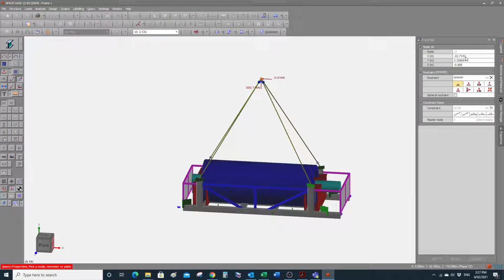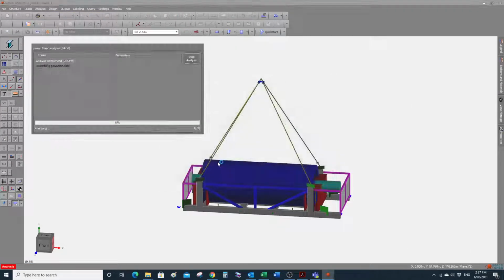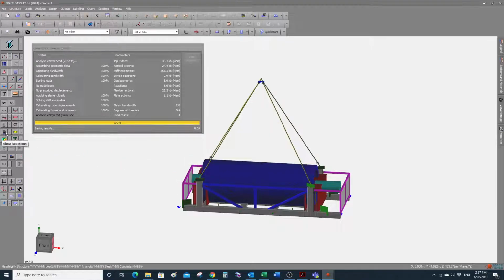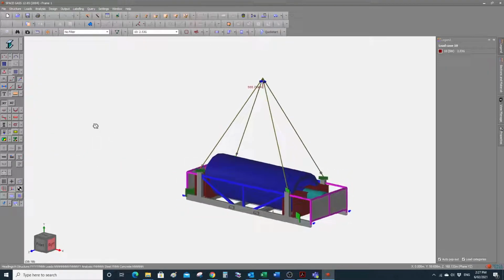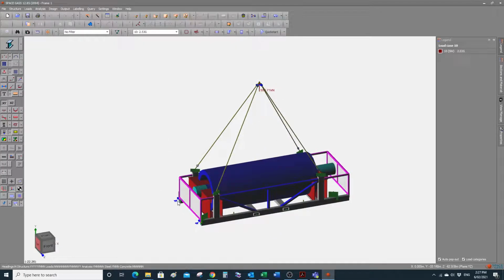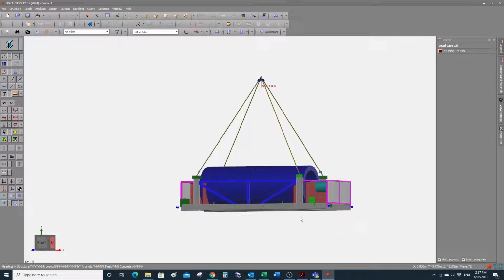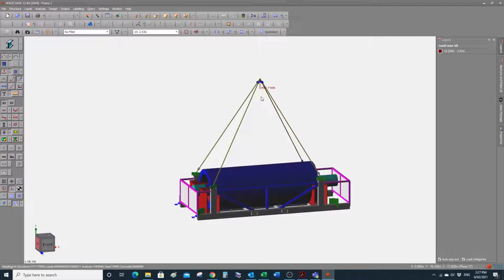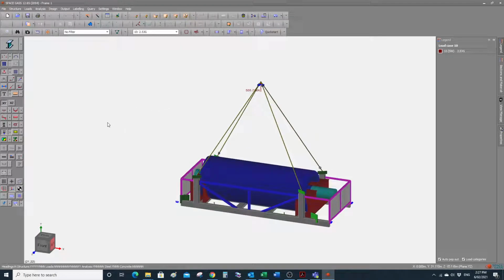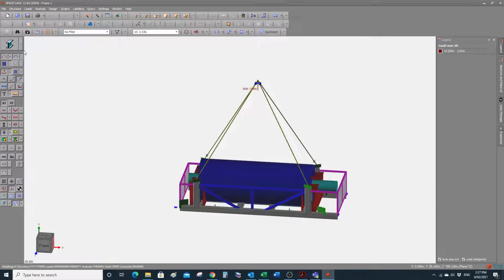That was too much, so I put 1.5, and hopefully this time it should be okay. There we go. We don't have any further horizontal reactions. Our soft springs are kind of idle, they are not taking any load, and my hook has got only vertical force to 2-digit, of course, and that's accurate enough, I believe, for this analysis.